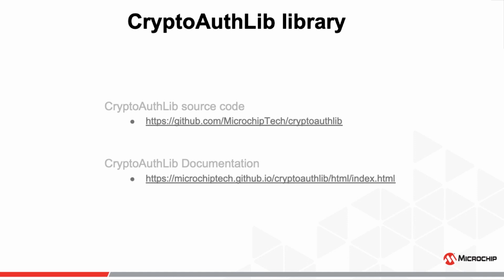The device comes also with a library. It's called the CryptoAuthLib library. It's a library that lives in the microcontroller and that keeps the system, the secure element, completely agnostic of the core that's being used. It could be a microcontroller, microprocessors. CryptoAuthLib has all the low-level API to talk over, in that case, I2C between the microcontroller and the secure element. Here you have the link. The library is open source. Please participate on our GitHub forum and ask your questions right there.